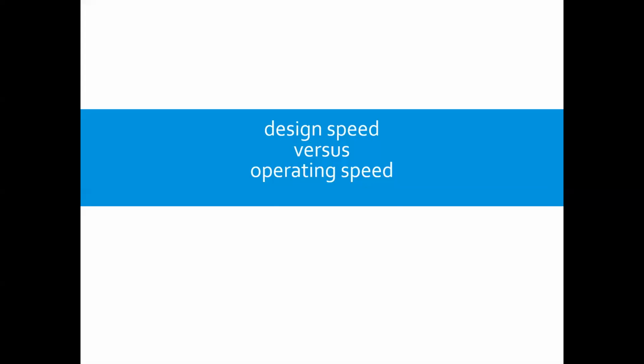Using this design speed, the design values for geometric elements of the roadway are selected. The designer is given some latitude in selection of the design values of the geometric elements. However, there is no quantifiable method to examine how the selection of different design values impacts the resulting vehicle operating speed on the road facility.